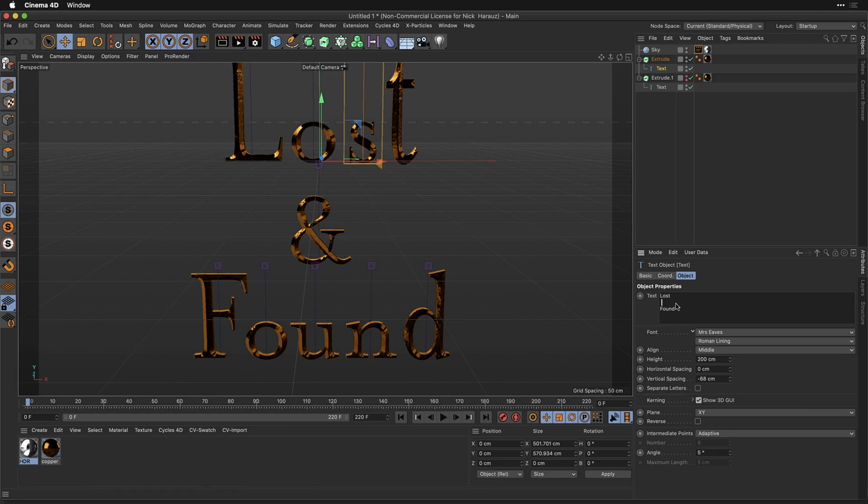The reason that I press the space bar to remove the "and" is because the kerning parameters use the letter position within the text, and if we delete a letter, we're changing which letter the parameter applies to. Now by replacing the letter with a space, we're retaining the number of letters.